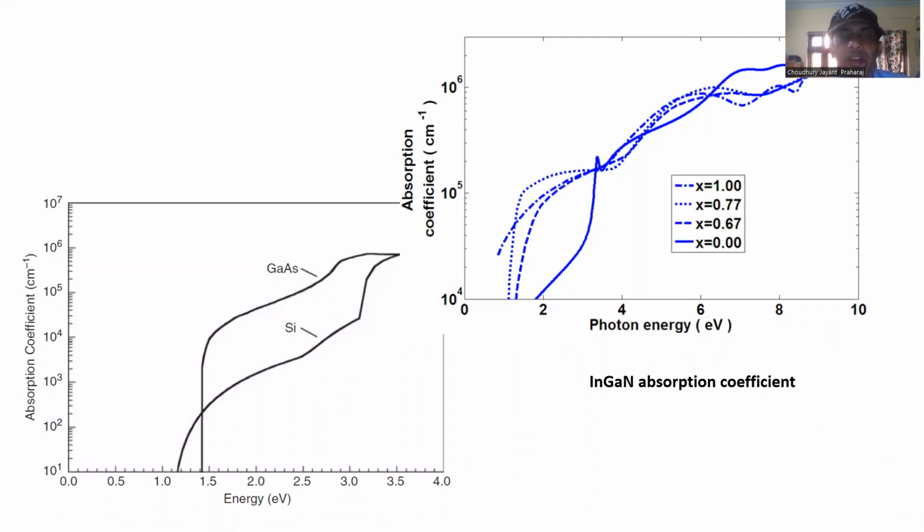Remember, there's a top contact and a bottom contact, and contacts have contact resistance. The contacts aren't completely perfect. There is a resistance drop in these contacts, a nonlinear kind of. We try to make it more linear, but there is a resistance drop in these. There is a voltage drop at these contacts, and they need to be optimized.